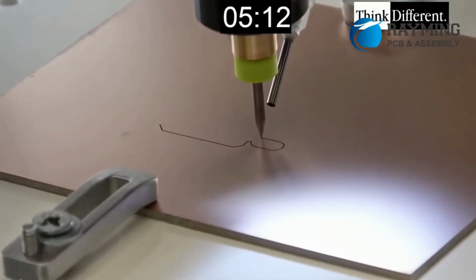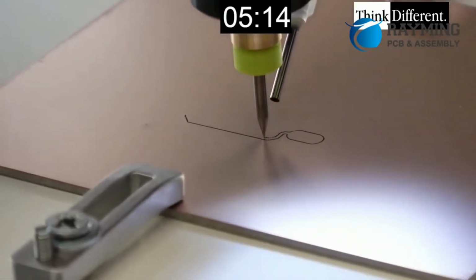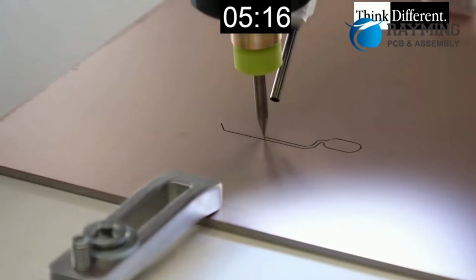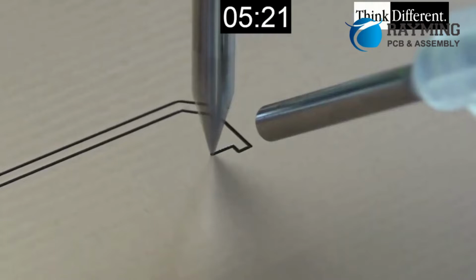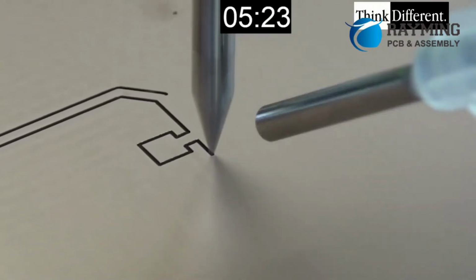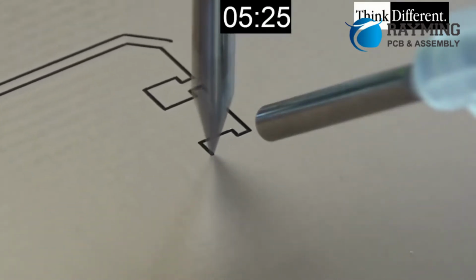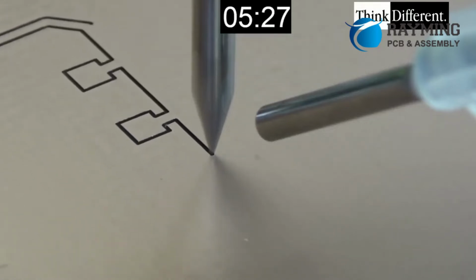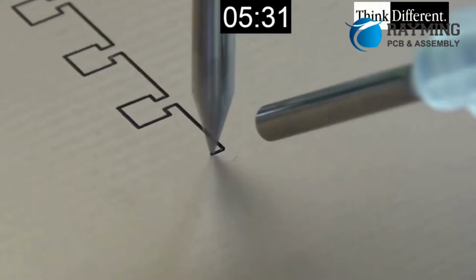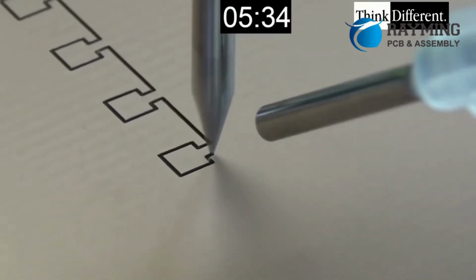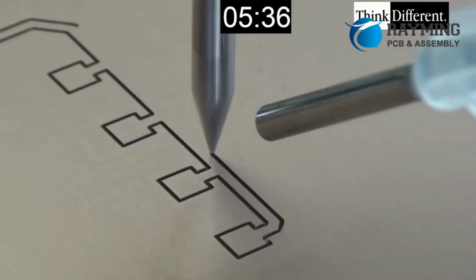Once you've made your PCB layout, you'll need to print it out. Remember that these blueprints don't print on an 8.5 by 11 sheet of paper, but on a plotter printer. This plotter printer prints the PCB design as film. This film is similar to the transparencies you might have seen in school. It's like a photo negative of the board. Remember that clear ink represents copper pathways, and black ink indicates areas you will remove.